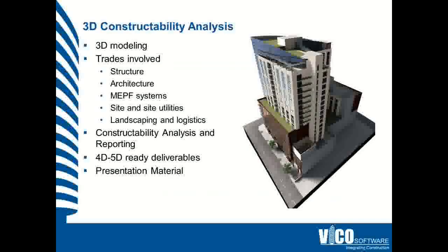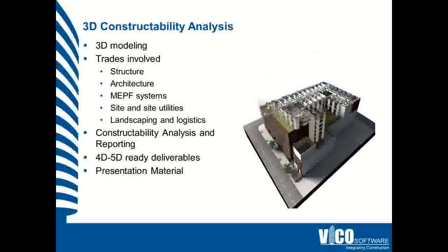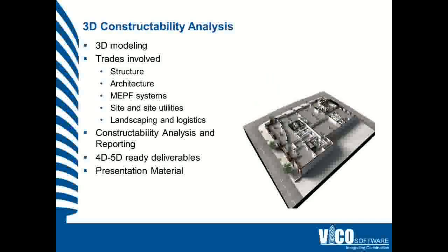3D constructability analysis. This has become throughout the years one of our basic deliverables, and we do it on all projects. We do so because as we build the models, I can assure you that we always run into issues, let it be missing pieces of information or collision or contradiction between documents and different trades, and we just don't want to keep these issues to ourselves. We rather create nice reports and give these to you. And you will be able to use that on site.